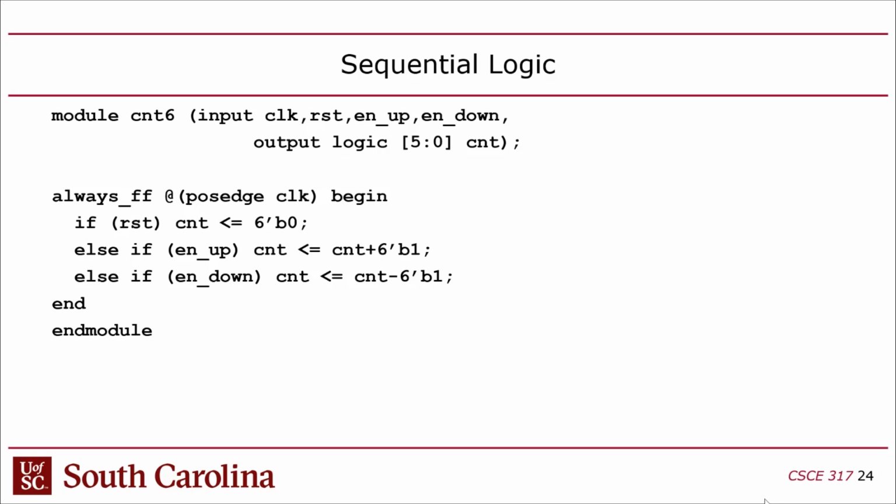By the way, the reason I'm focusing on this is that the protocols we studied at the beginning of the class, SPI and I2C, are all circuits that would be implemented in sequential logic, because they all have a sequence to them. Like SPI: the slave select goes down, and then I have to count 8 bits off. That is basically what's happening in something like this, where you have a counter counting up or down, keeping track of a count called count.